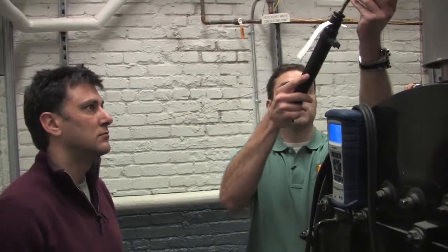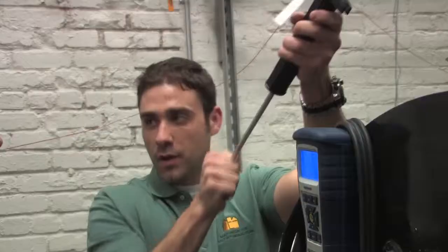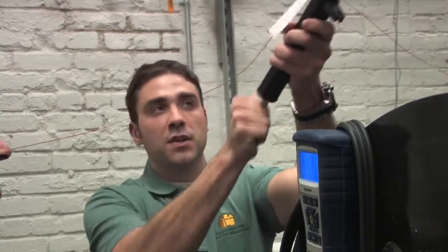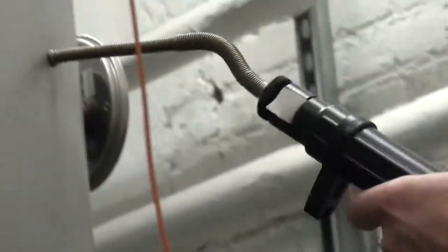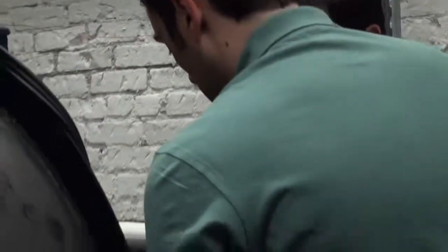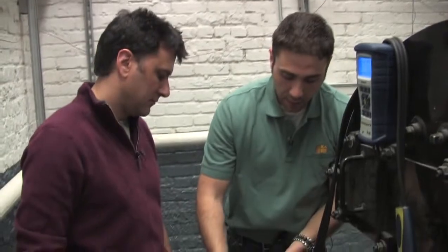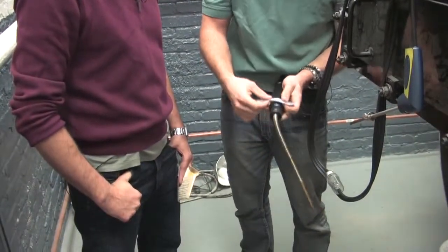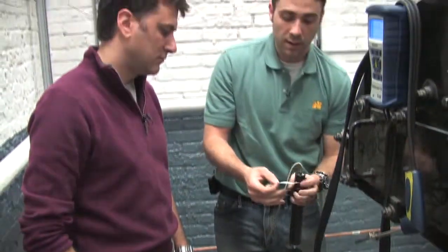So what you'll do is that where you drill your hole, where you test, you're going to put the smoke tester inside. So what you're going to do is you're going to pull this 10 times. So you go 1, 2, 3, all the way to 10, just to get a good sampling and make sure that you're pulling enough flue gases through and making sure that it's going to get a good reading of it. When you're done, you have your 10th time, you're going to take it out, just make sure the tip is very warm so you don't hurt yourself, and you're going to open up the clamp and you're going to take a look at the spot. So we have a little spot on here, and it's not very clean, as you can see.